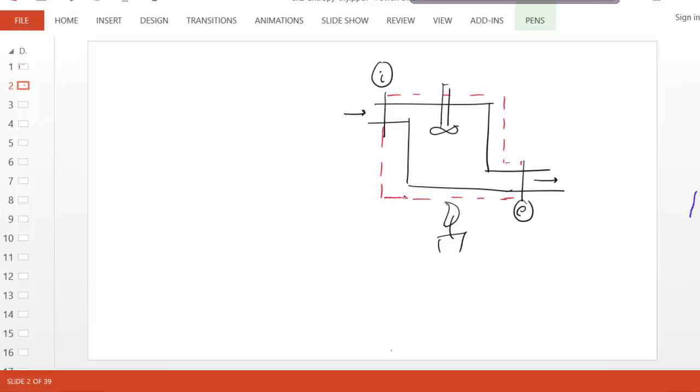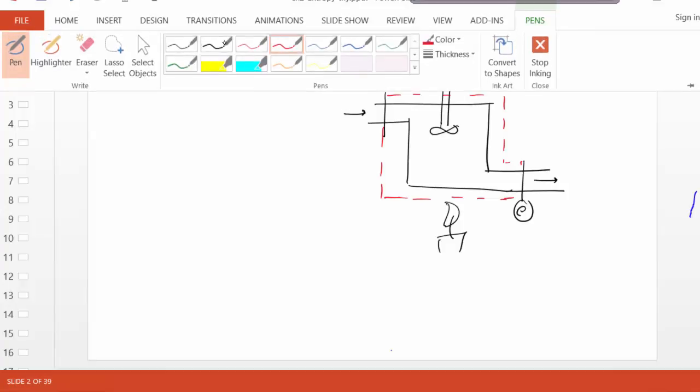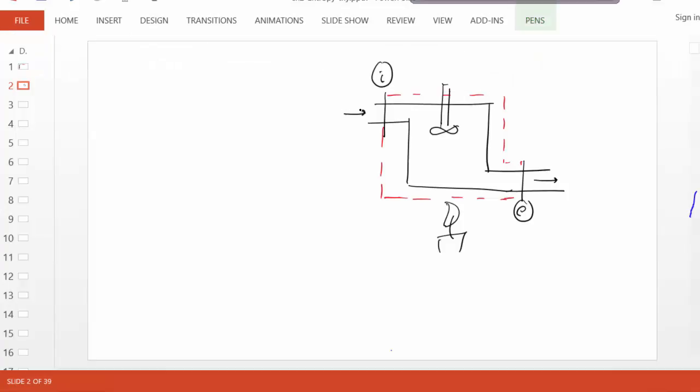Okay, so we want to develop the entropy balance equation for this system. Simple thing first. We understand as mass goes in, it carries entropy with it. So entropy transport S dot would be simply m dot S, just like if you recall that flow energy transport is given by equations such as this. These are called transport equations.